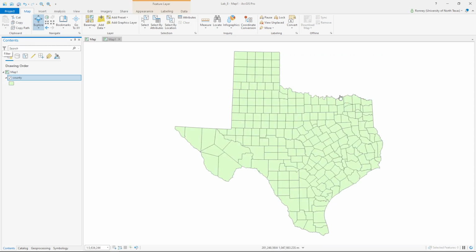There we go. It's not located in Africa anymore. This is in meters right here, instead of decimal degrees like we had earlier, because a projected coordinate system measures things in metric or imperial units instead of decimal degrees. It's kind of difficult to explain, but it doesn't base things off degrees, and degrees are measured from the center of the earth out to the surface. That's how your degrees work. But anyway, enough about that.